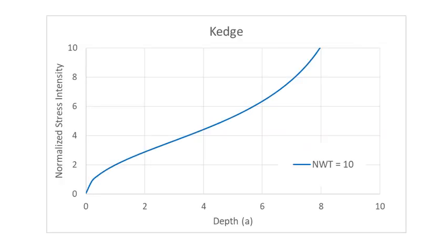So here I do a simple plot of that stress intensity factor. On the y-axis, I've got a normalized stress intensity, so I'm assuming a uniform applied stress of unit 1. And on the x-axis, I have the depth. In this case, I've gone from 0 to 10, assuming a nominal pipe wall thickness of 10 millimeters perhaps, and then the depth accordingly would be in millimeters.